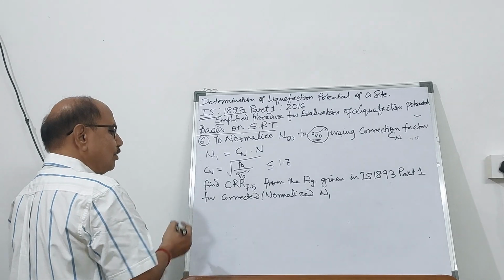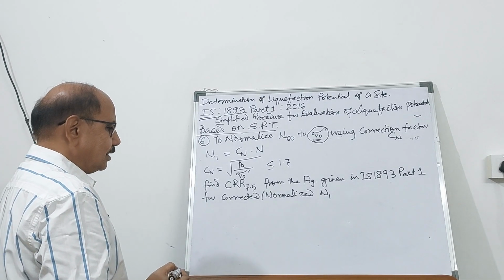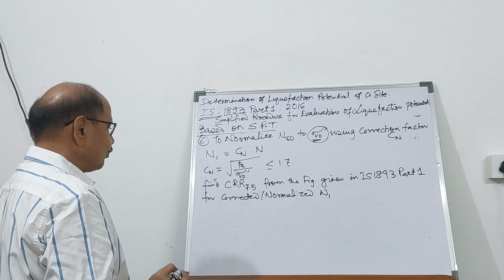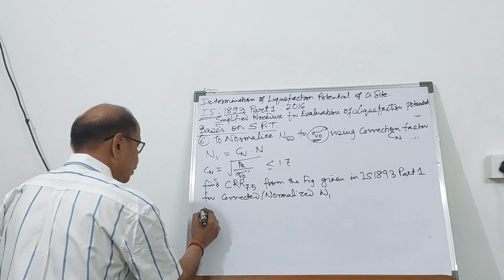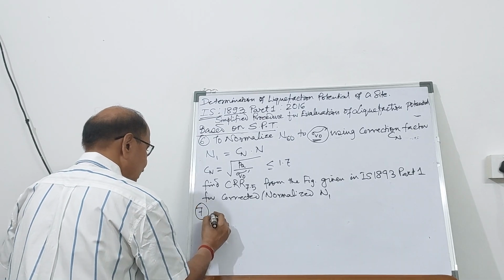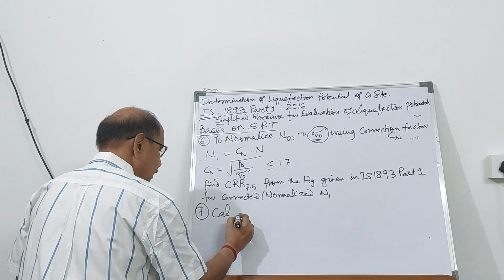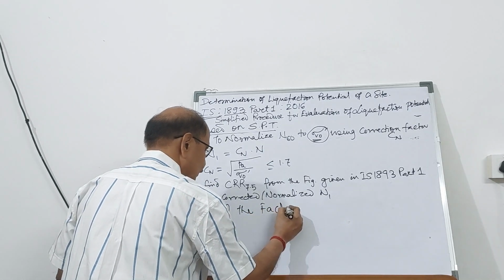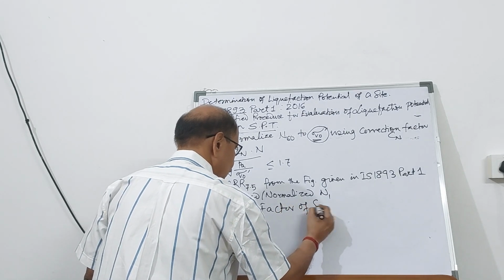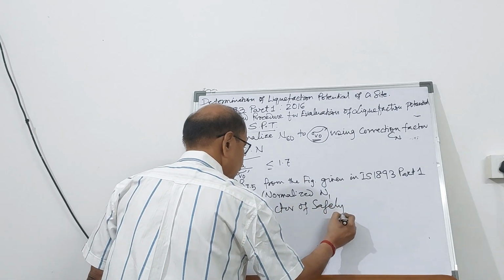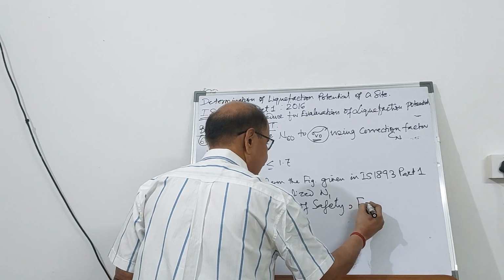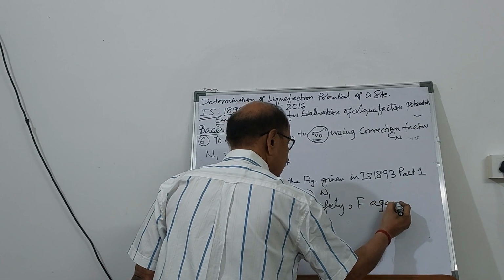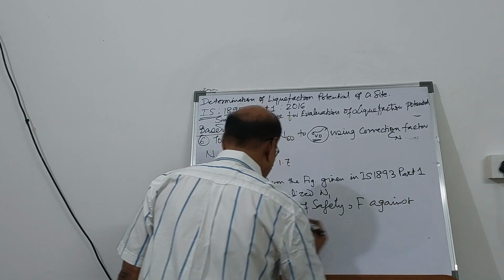So having got the value of CRR, you can next calculate the factor of safety F against liquefaction.